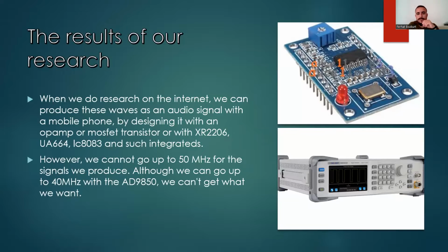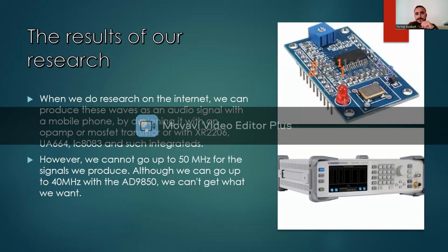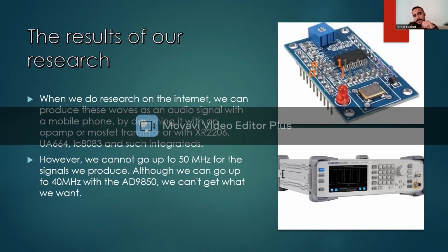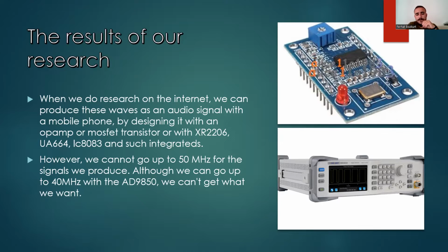When we do research on the internet, we can produce these waves as an audio signal with a mobile phone, by designing it with an op-amp or MOSFET transistor or with an integrator like XR2206, or we can use Arduino or Raspberry Pi, but we cannot go up to 15 megahertz for the signals we produce, although we can go up to 14 megahertz with the AD9850. We can't get what we want.